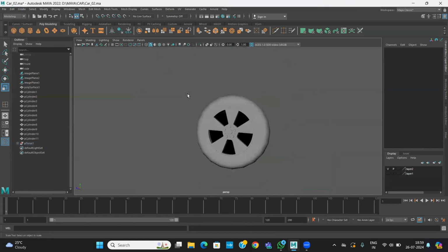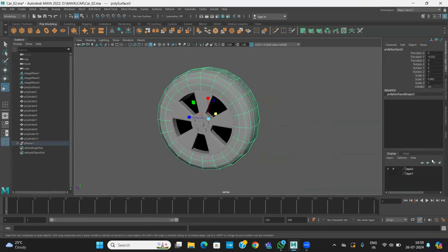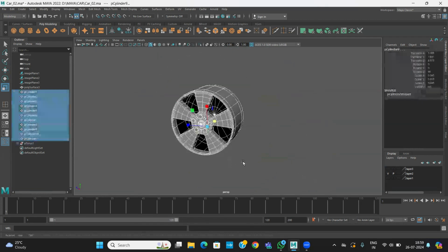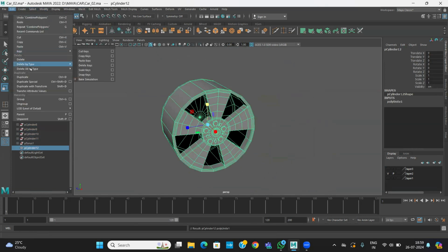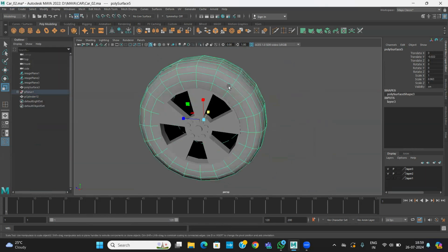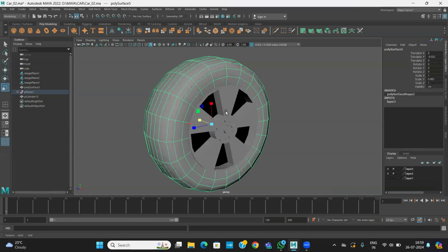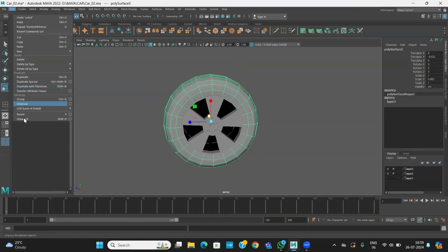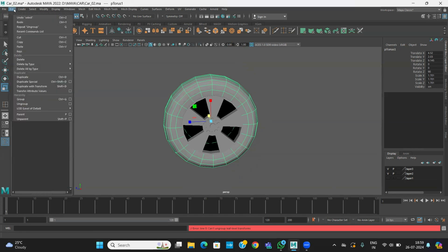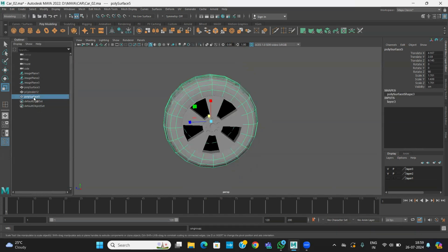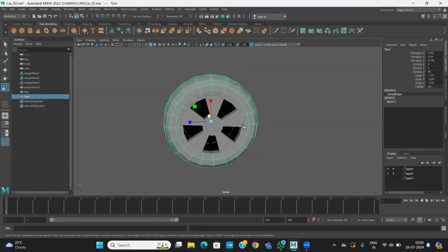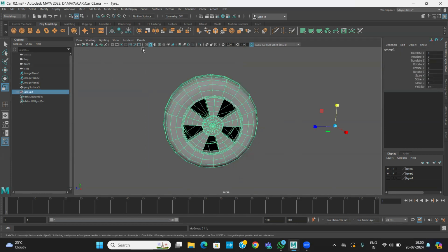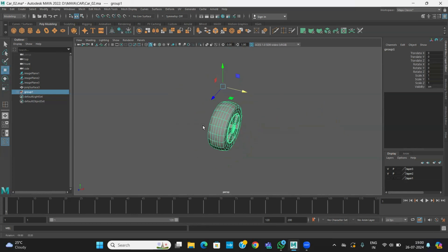We're not doing texture now. What you should do is make this another layer. All those things you combine into one layer. So maybe mesh combine, edit, delete all the history, fine. And this is another one. This also, edit, ungroup, right? So this is called your tire, you name it, and this is called your ring. Both will have a different texture, so let them be different objects. You can select both and ungroup, like Control Z, and this will be fine.